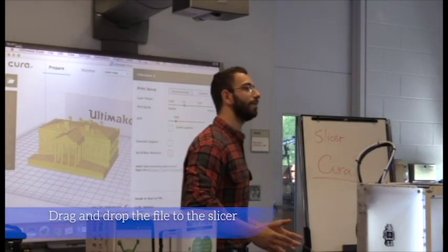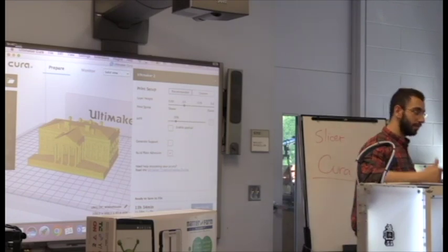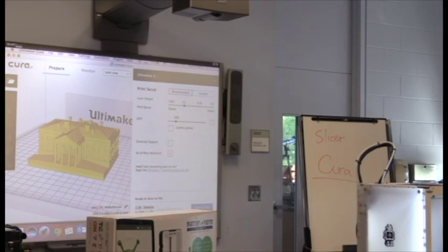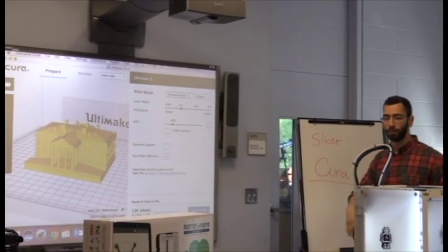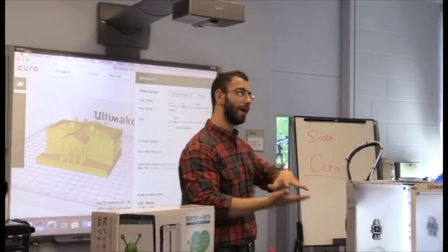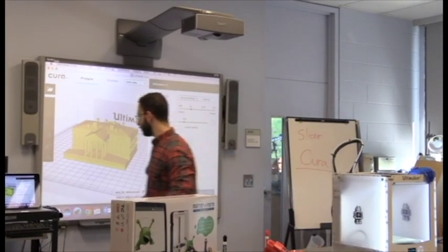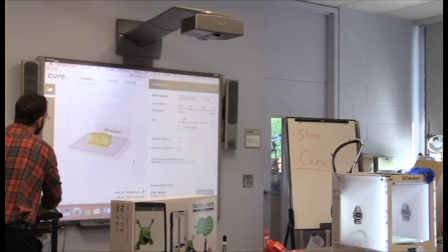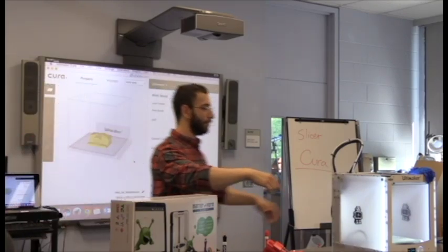This is what you really need to 3D print. This is step one. Step two is going to walk you through the printer. Okay, this is when you really pay attention. The slicer file: you grab the STL, drag and drop, and it goes right into there. That's kind of your work envelope, with the different coordinates you have. The bigger the printer is, the bigger the whole envelope will look. I can zoom out a little bit. Okay, right there.